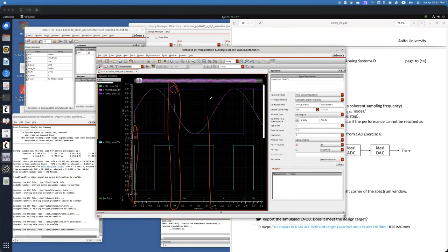And for 2 seconds, which is twice the period of the clock, we get this sample. And here, we get this sample because we set the sampling frequency to 1 megahertz, which means 1 over 1 microsecond. So from this settle time, which we set as 0 seconds, we get samples 1 megahertz clock period later, and then the next sample, and so on and so forth. So FFT runs this way within our CAD virtual environment.